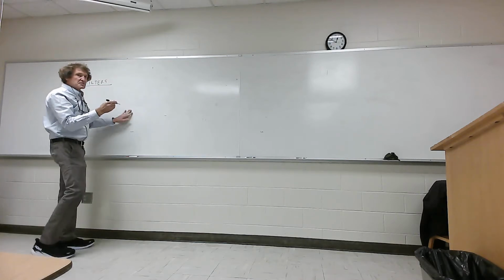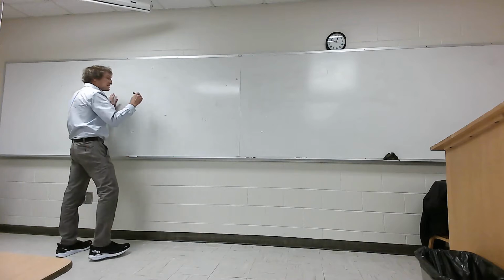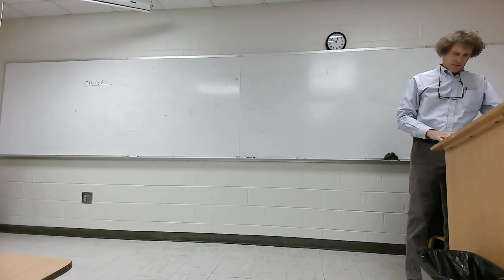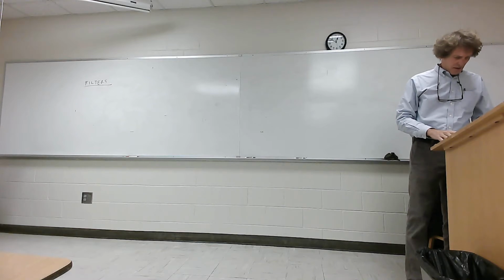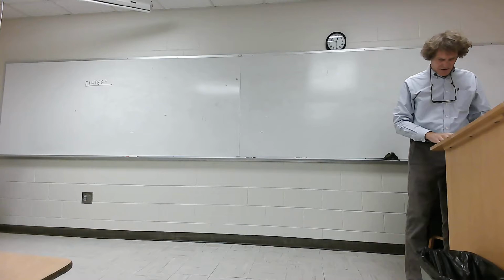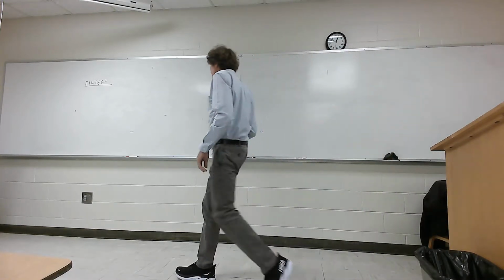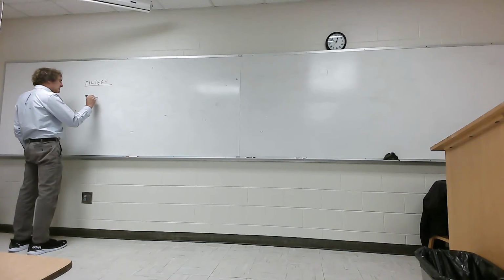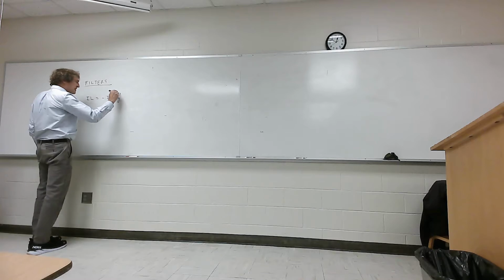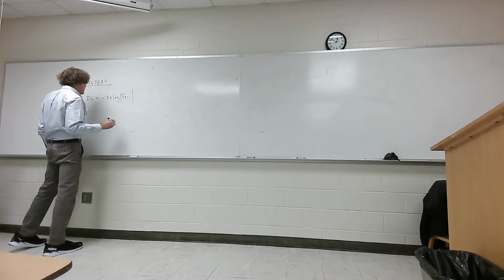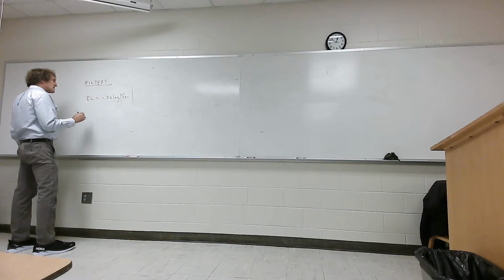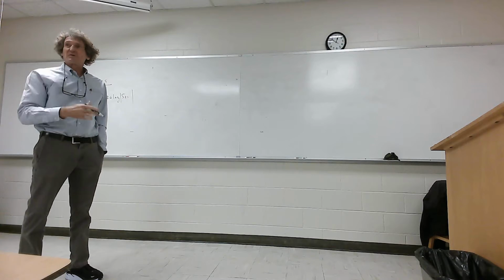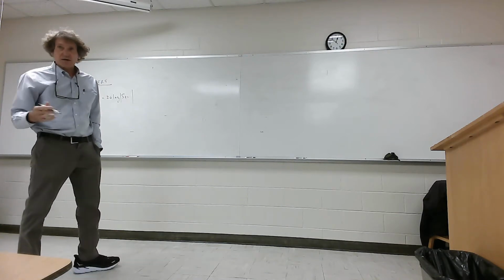When we talk about filters, I'm going to do it the way he's actually doing it. This is in his book on page 579. So with filters in the S domain, at least, the insertion loss is minus 20 times the log of the magnitude of S21. That's something they talk about a lot, the insertion loss, but a lot of times you can have an amplifier, so this will actually be negative, it'll be a gain. Just try to understand it.